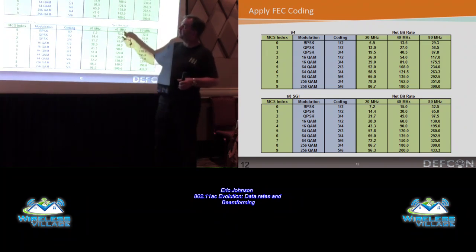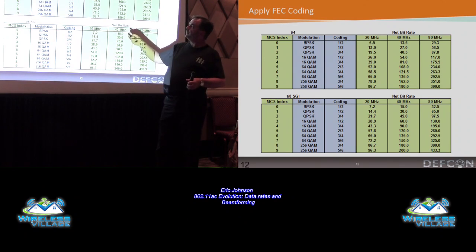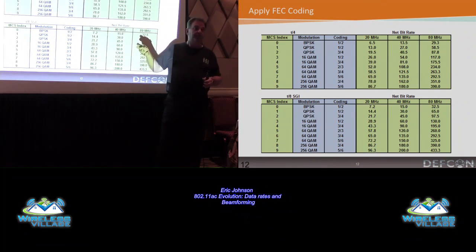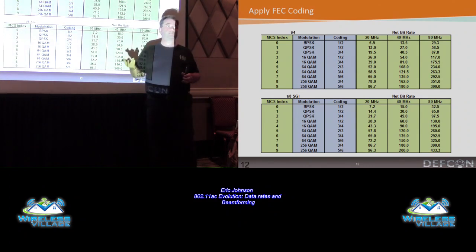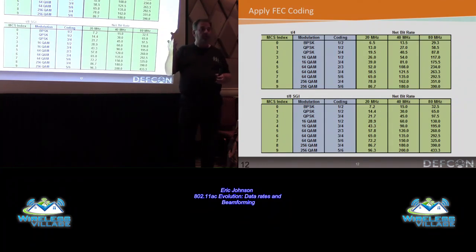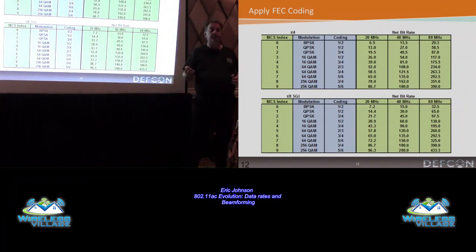This is if you're really far away and you're connecting at low signal strength. It's probably going to be connecting at BPSK. On BPSK, we use what's called 1/2 coding, which means for every 1 bit of useful information that I'm sending, I'm actually sending a total of 2 bits. So there's 100% redundancy in this system. So that 13 that I had before has now become 6.5, because only half of the bits that I'm sending are useful.